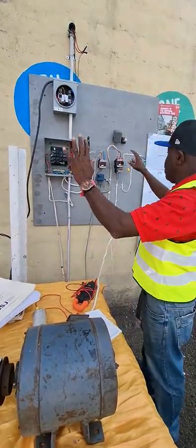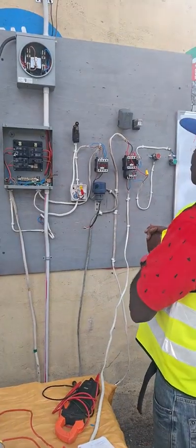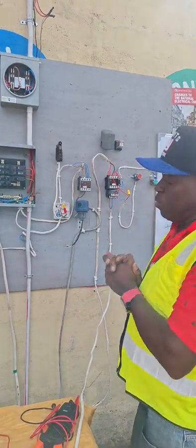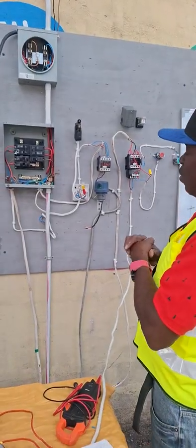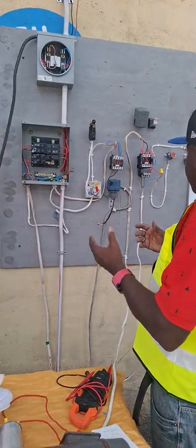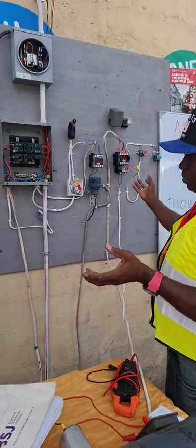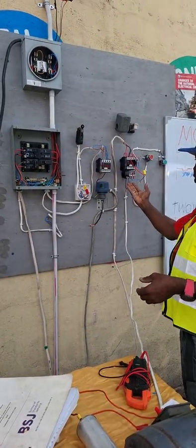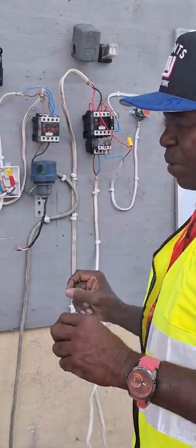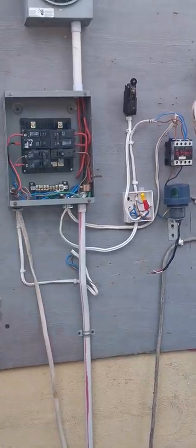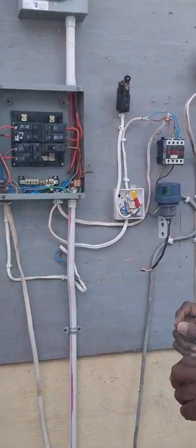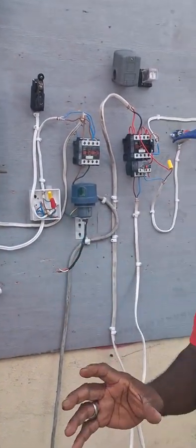So remember, this is now our reference circuit that I have here. In this case, the motor circuit is normally supposed to have overload and ground fault protection, which will be provided by the breakers. Where the overload is concerned, we normally have the overload as part of the starter, and that overload is there to protect the motor from excessive overload. If the overload is too high, the motor will trip, protecting the motor from burning up.